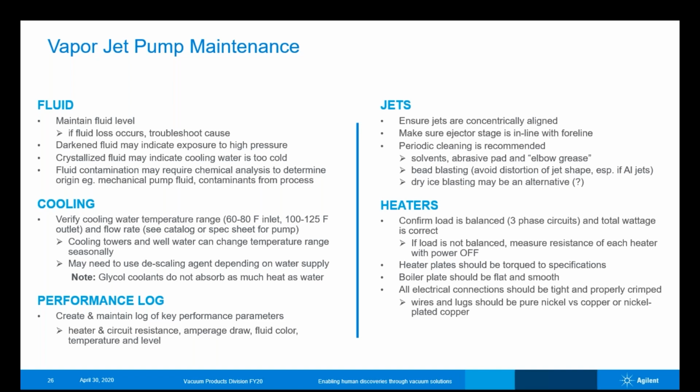Typically, pumps are dismantled from the system, taken apart and cleaned. When putting them back together, you want to make sure that the jets are aligned, and in particular that the ejector stage is in line with the exhaust or the foreline of the pump. We've seen that in different cases.